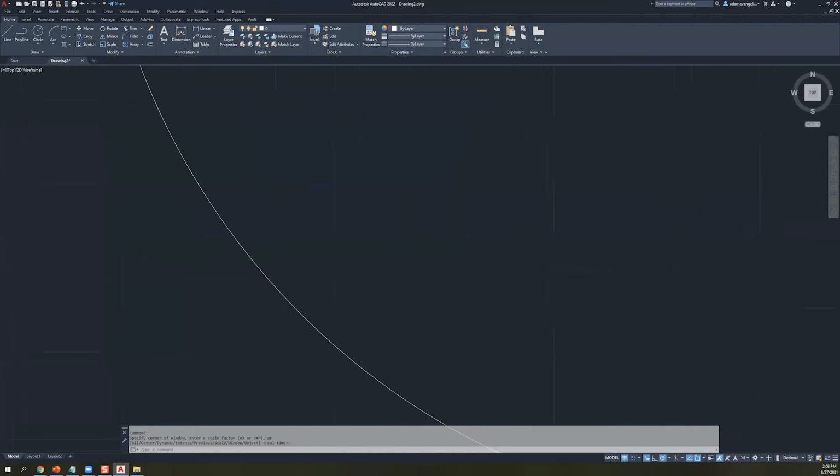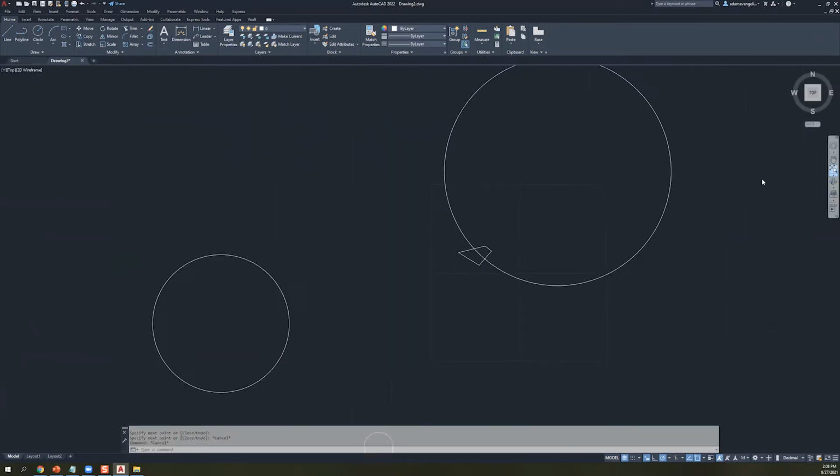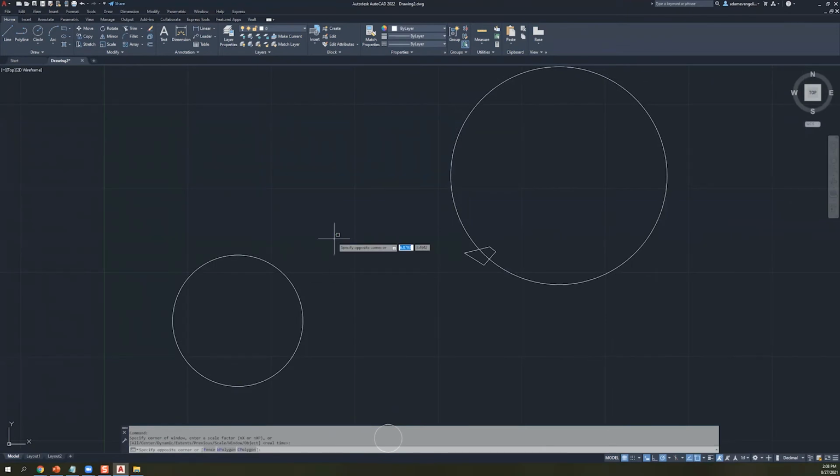And if I were working super close over here and starting to draw lines, having a good time like this, and I want to zoom out right now, I could easily just go over to Zoom Extents. That'll zoom me back out so I can see everything that's going on over there, okay?